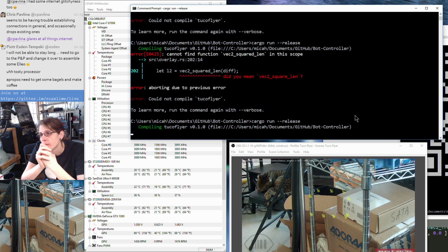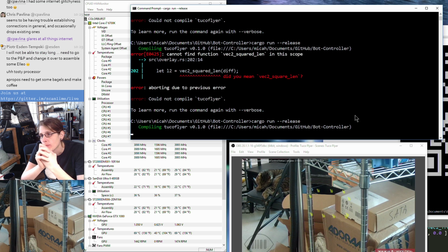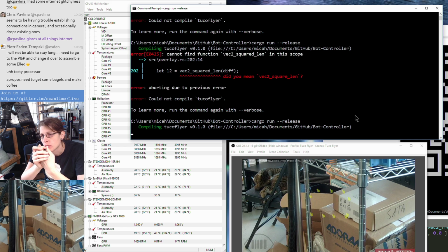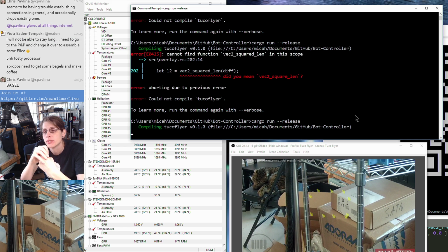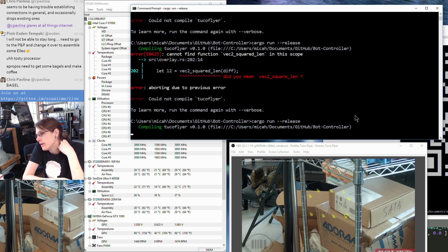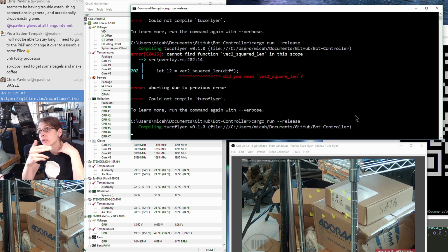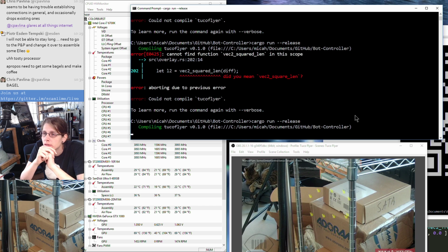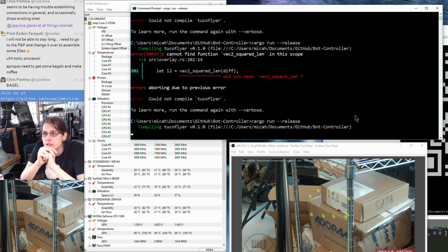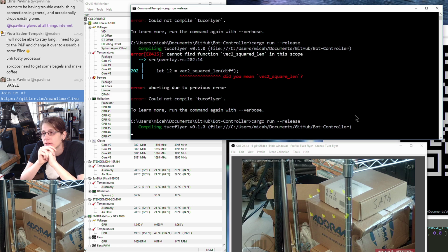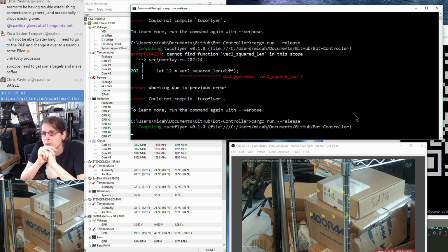I haven't quite decided what to do with the limiter yet. Right now it just has a proportional control loop where if the gimbal is past any of its limits, it applies a proportional control velocity in the opposite direction. But the result is that that's super bouncy right now, and maybe I just need to turn the gains down and move the limits in a little bit.